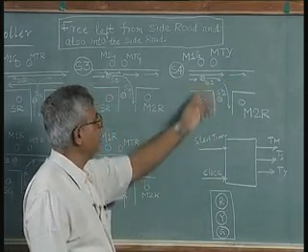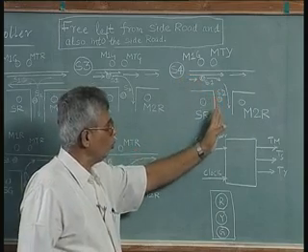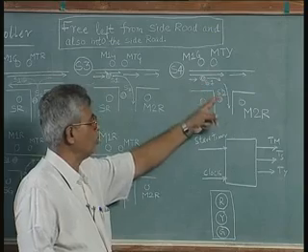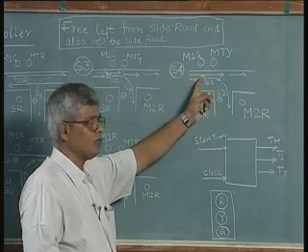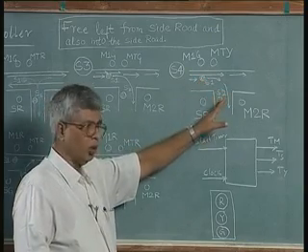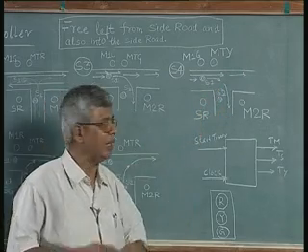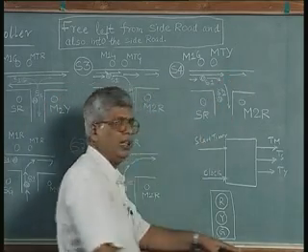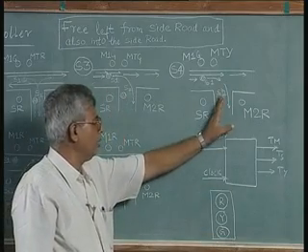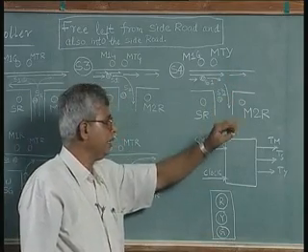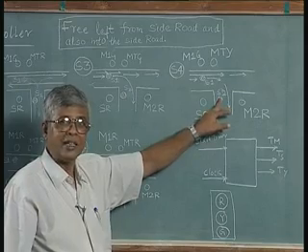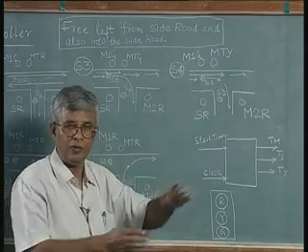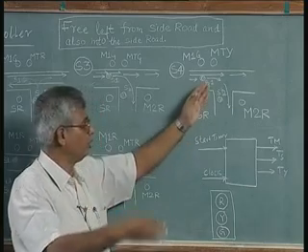On the other hand, there is no car waiting, even though we decided one of the two sensors, S1 or S2, was on. It so happened that S1 was the reason for that, and there is no traffic waiting at S2. We do not have to unnecessarily waste our time making a green for the turn from the side road to the main road on the right hand side. So at this point we will only check S2, we will not check S1. S1 we have already given a chance, it has to wait for some more time before it can be tested again.